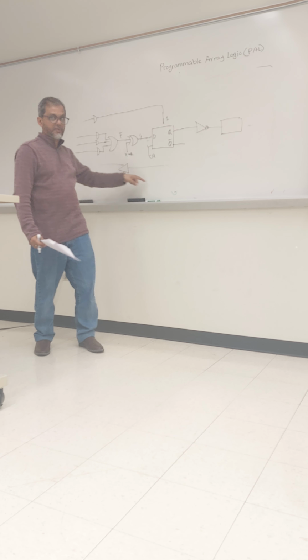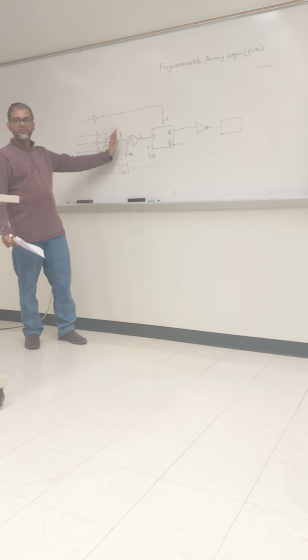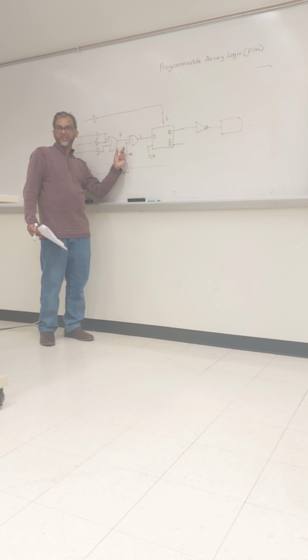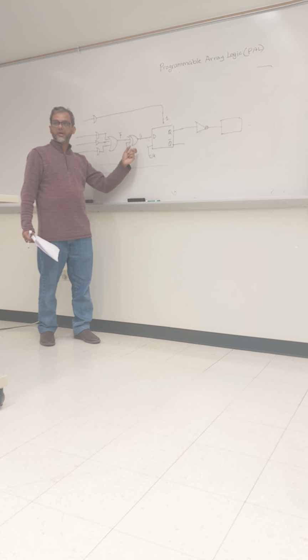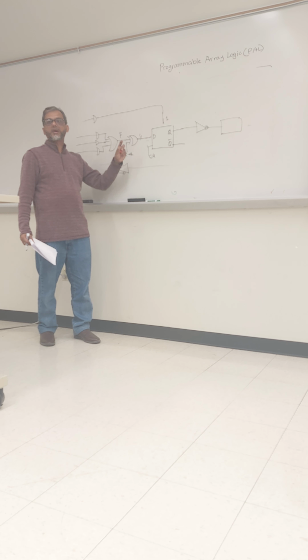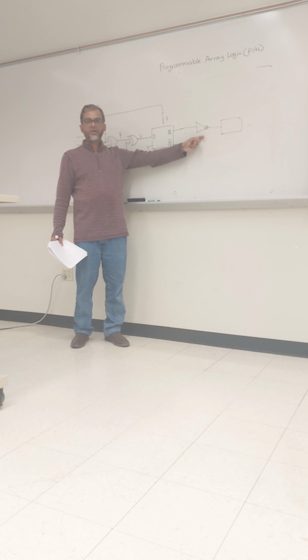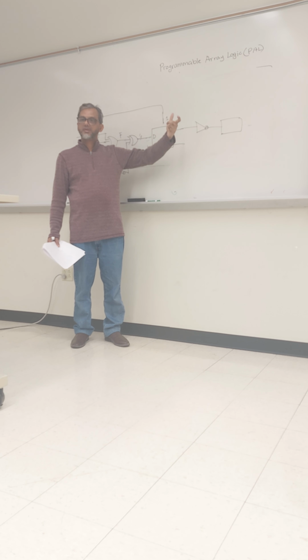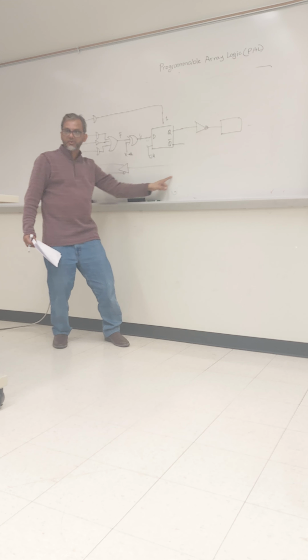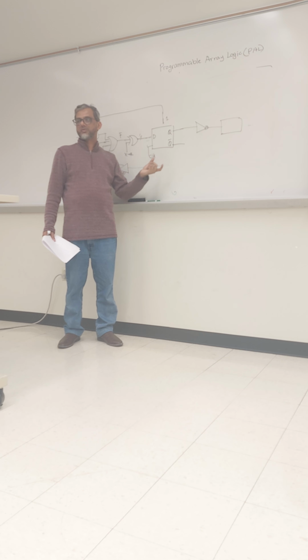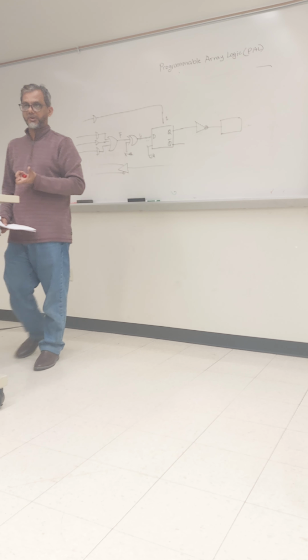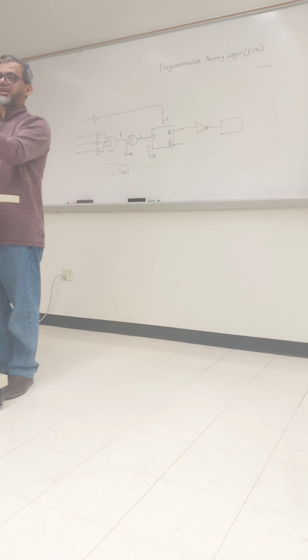This is still in the macro cell. In the macro cell, we had nothing previously. Previously, we took output from just here. Then we tried to understand, okay, if we put another logic gate, here we add the XOR gate, we see that we can make the functionality in true and complement form. Then we add the buffer circuit. Then we said, okay, here now we can use it as a high impedance inverter circuit, then we can give the input back. Now we are adding a memory cell here, so that we can even store that information, so that we can give that information to the next stage.